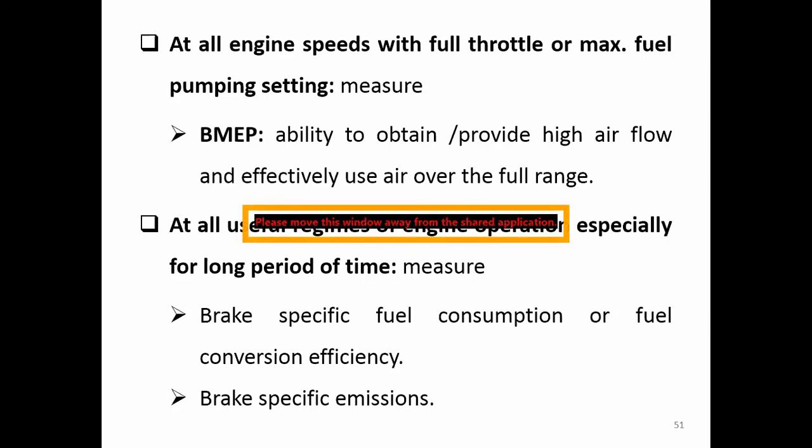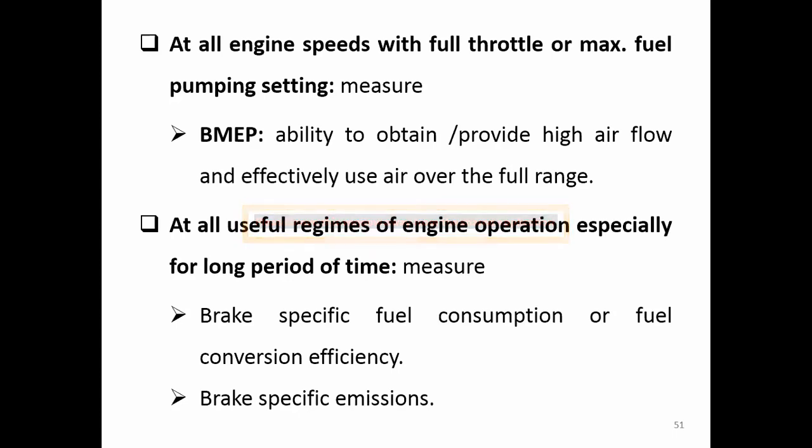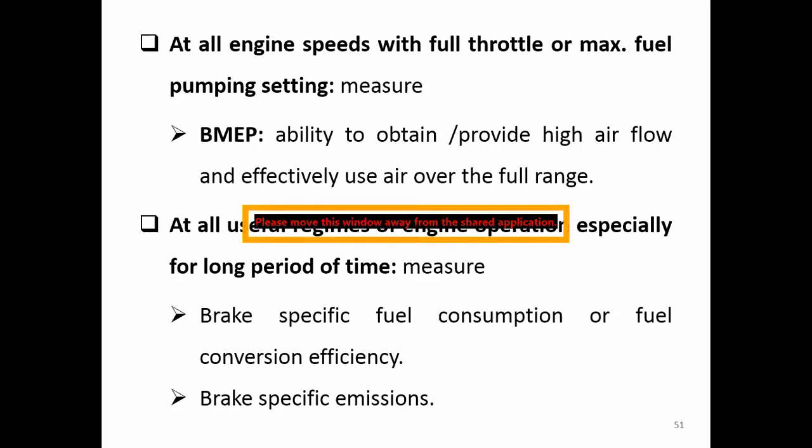But for the last one, you will run this engine at one certain condition and run it for a long time, right? For this, you want to see the brake specific fuel consumption or the fuel conversion efficiency. That is, if this engine runs for longer hours, how much money you have to pay. And also the brake specific emissions, right? Because you run the engine for a long time, you want to see how much emission this engine will emit from its running.